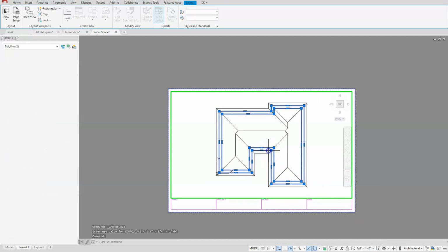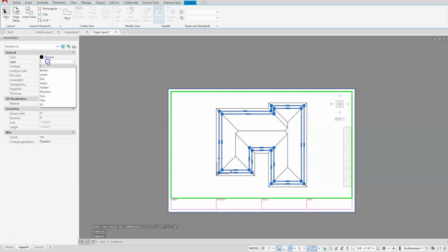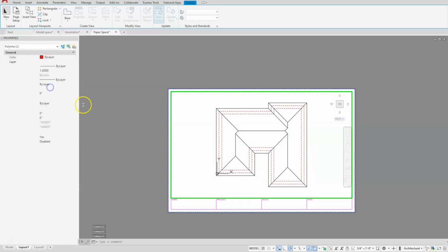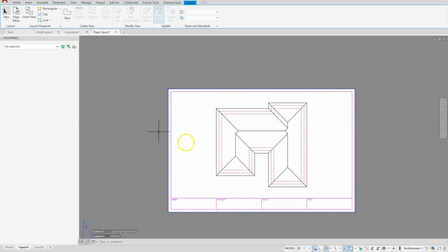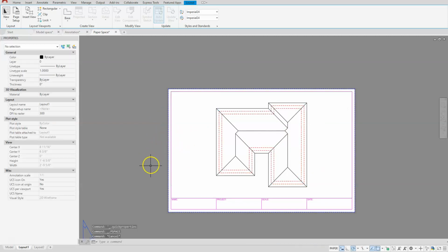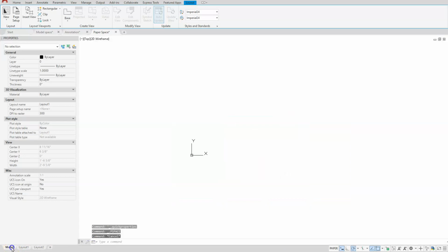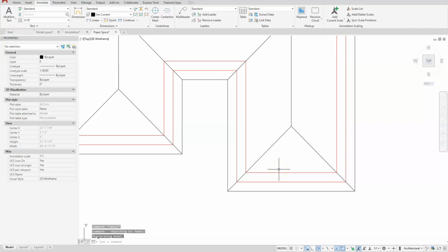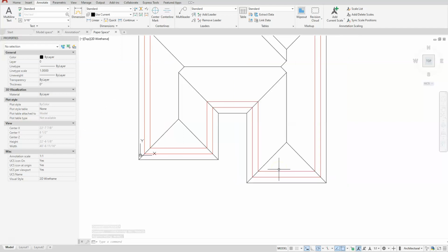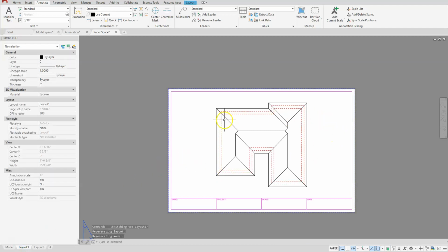And since we have our title block in, let's go ahead and move this to the correct layers. So if I go to Hidden, you can see that my line types have already been adjusted. I'm going to double click on the outside to get out of the viewport. Now once I jump back into the model space, you're going to see that everything looks normal because the line type scales here are not adjusted. And you don't have to worry about adjusting them because Paperspace is going to automatically do that for you on the outside.